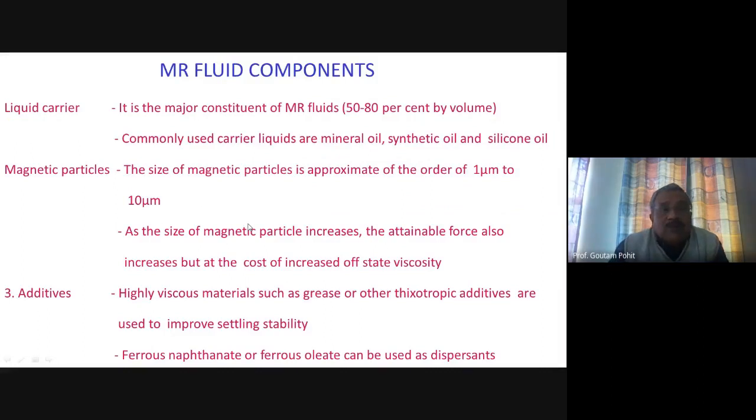And what are the components of MR fluid? Liquid carrier is the major constituent of MR fluids, 50 to 80% by volume. Commonly used carrier liquids are mineral oils, synthetic oils, and silicon oils. They carry the magnetic particles basically.